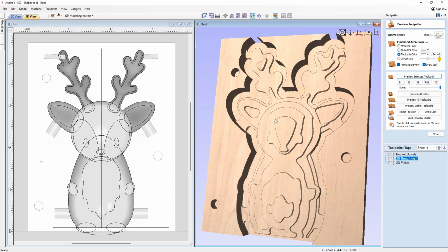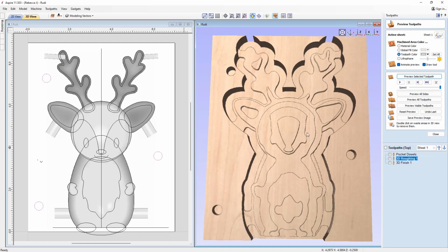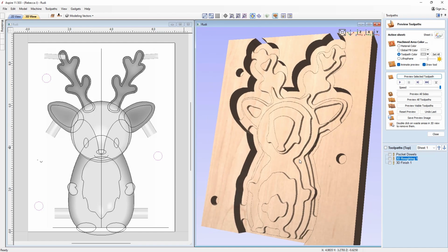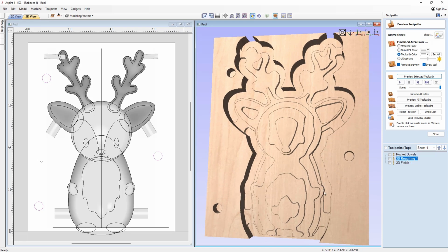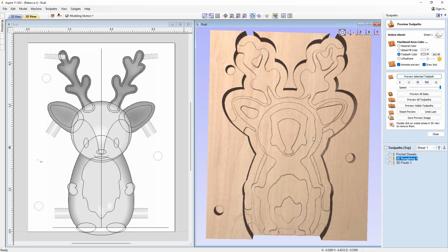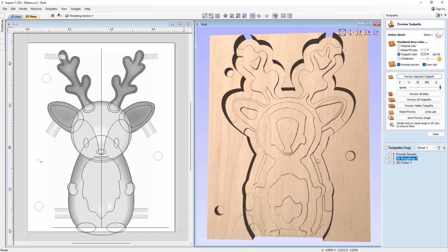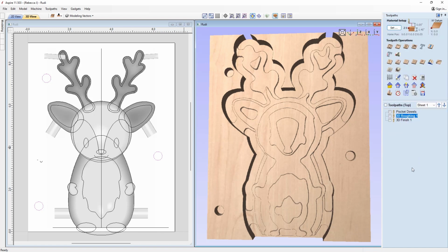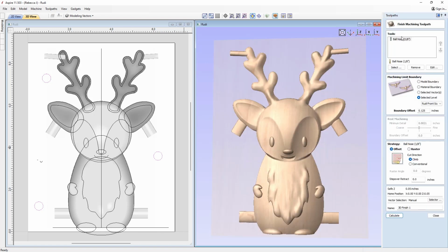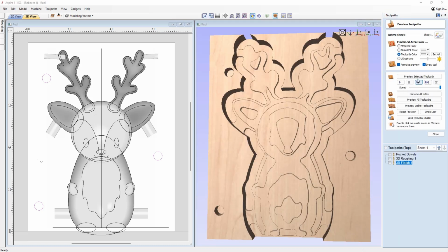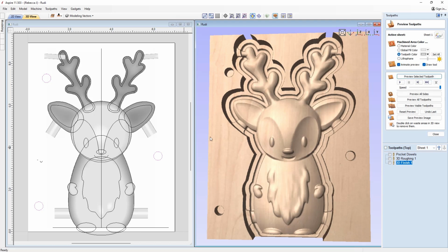Okay, so that's what that looks like. You can see all of the different steps in there. We've got a nice gap around the outside as well, so we're ensuring that our tools can fit in at the edge of our part. Then we can close out into the finishing toolpath using a 1/8 inch ball nose. Again, same level, with the offset matching the diameter of the tool.